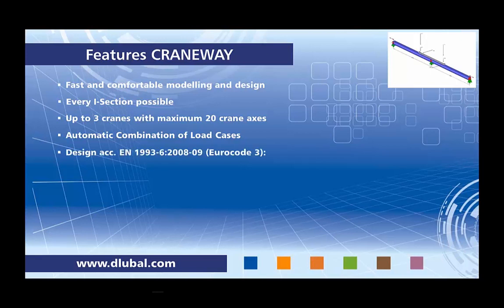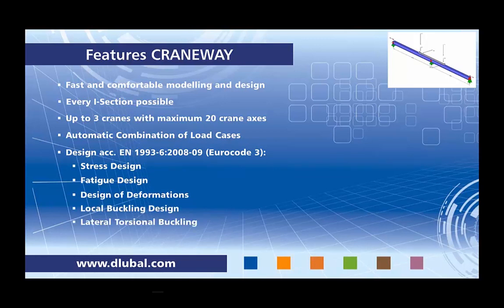The design is according to Eurocode 3 Part 6, which includes the stress design of the crane, fatigue, design of deformations, as well as the local buckling design and the lateral torsional buckling design according to the P-delta method or second order theory, including the warping of the cross-section.